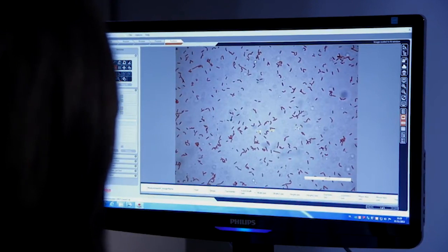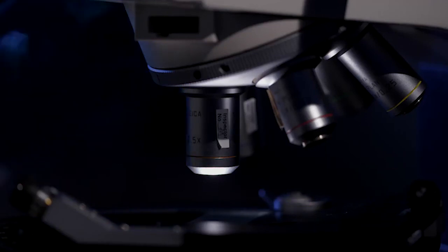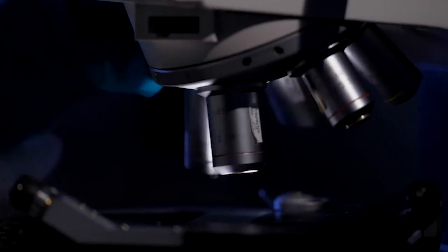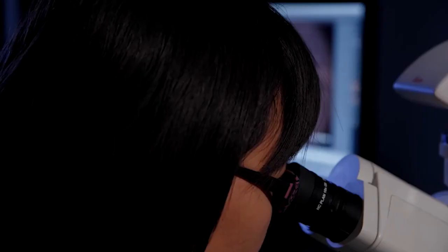These crystals are deposited in the crack, resulting in crack closure. Due to this, aggressive agents can no longer enter into the crack and the durability of the construction is improved. As the bacteria need to survive in the concrete without nutrients until the moment that the crack appears, they are added to the concrete mix in a dormant state.